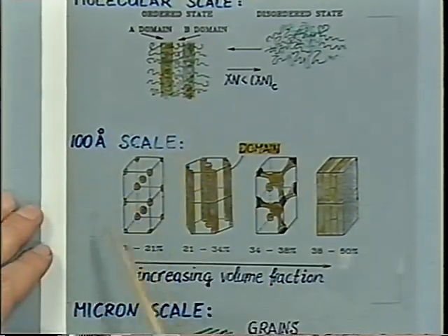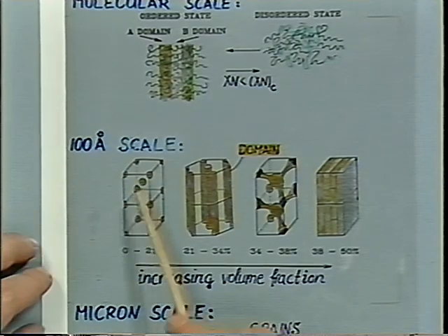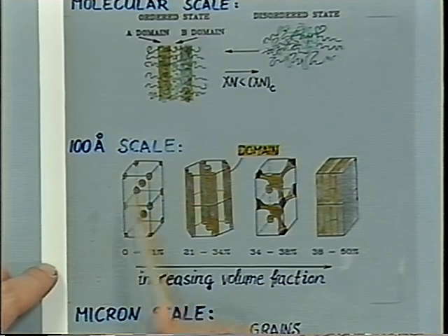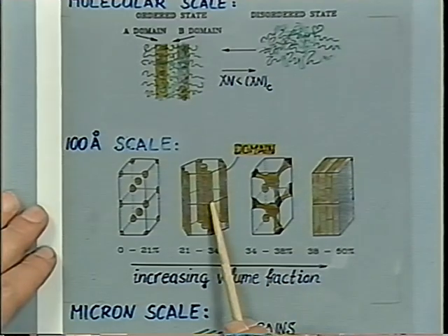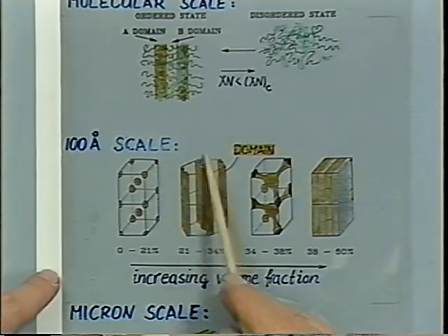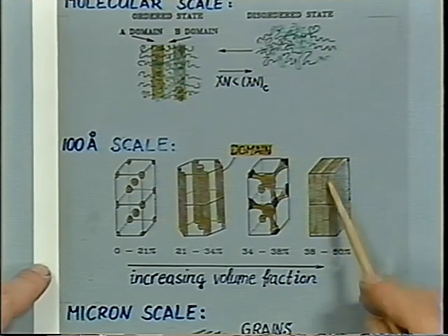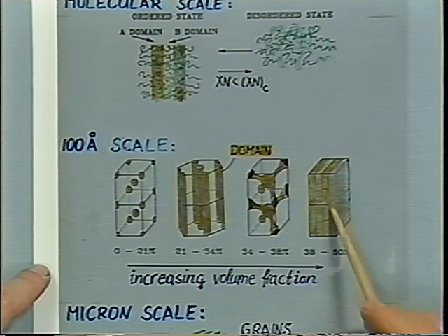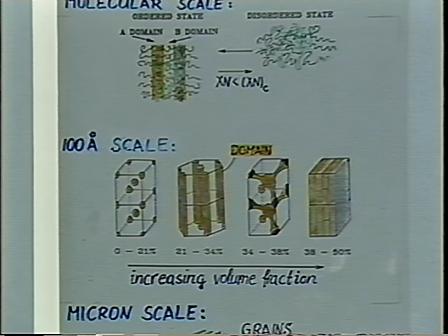phase-separated regions order, in some cases in form of a body-centered cubic spheric morphology, or we would have cylinders on a hexagonal lattice here, regular structure, or at intermediate morphology, the material forms lamellae of AB alternating. There's also a special case which occurs for diblocks where a double diamond structure is interpenetrating.